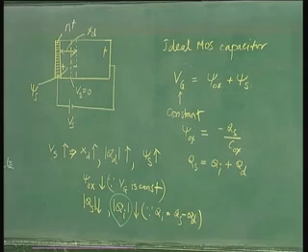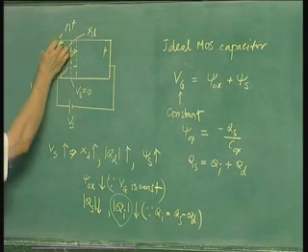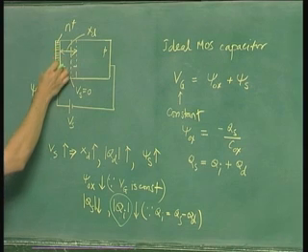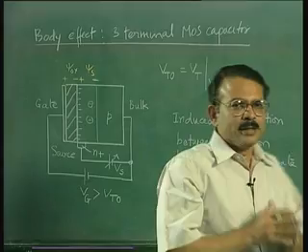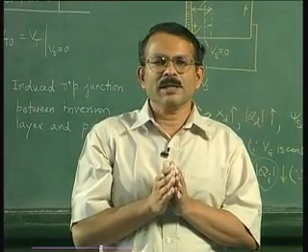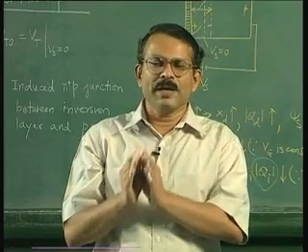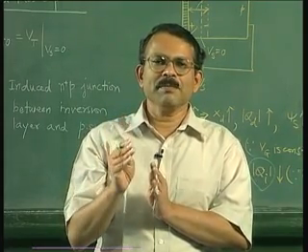So that means in this junction, as this depletion width expands, the amount of electrons in this n plus region will go on decreasing. Now therefore it appears quite logical that for some value of Vs, this inversion charge which is decreasing can become equal to 0.